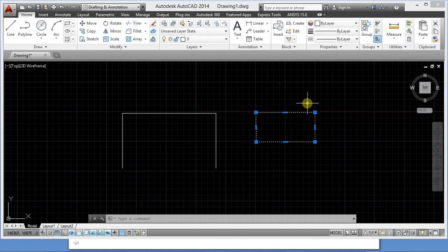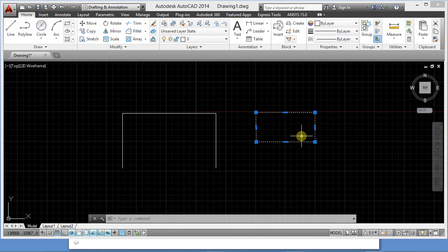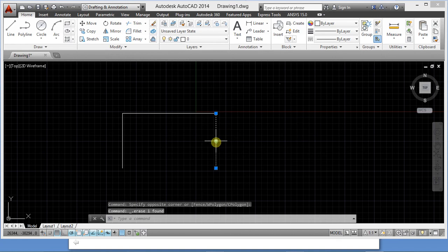So the difference between line and polyline is that with line objects, the sketch shows you the different lines as you sketch them. But in polyline, all the lines are recognized as a group shown as one sketch, while this other one drawn with lines is shown as different sketches. If I select one part like this, it will select everything. But here, if I select only here, you only select this one line. A line drawn with polyline is seen as one object, so if I delete here, the entire thing will be deleted. But if I select this one, only one will be deleted. So that is the difference between polyline and line. Just know that.